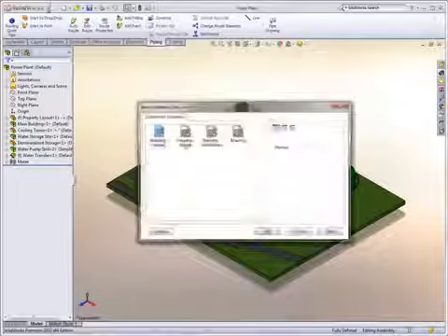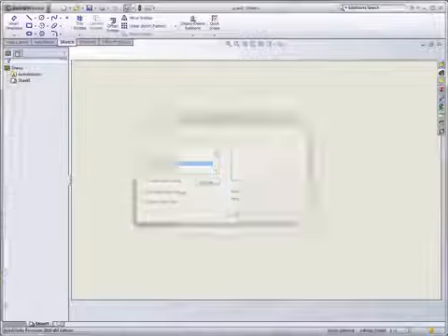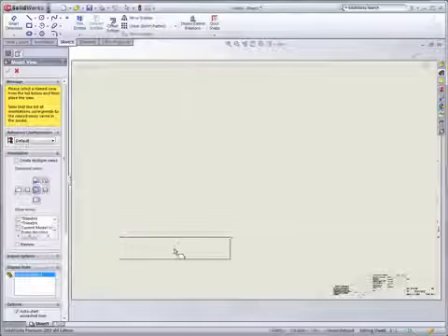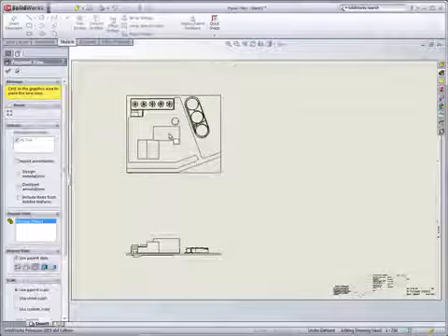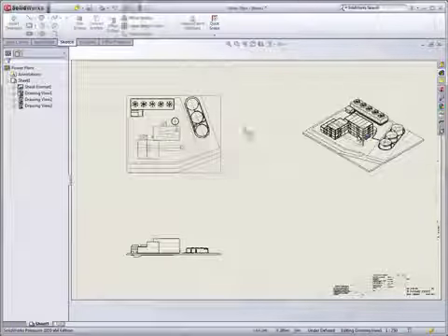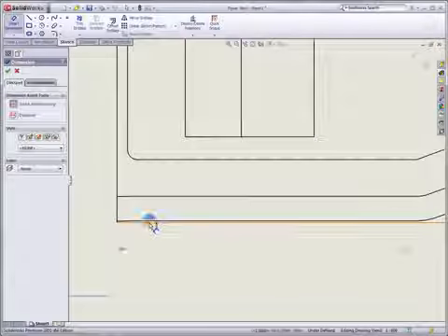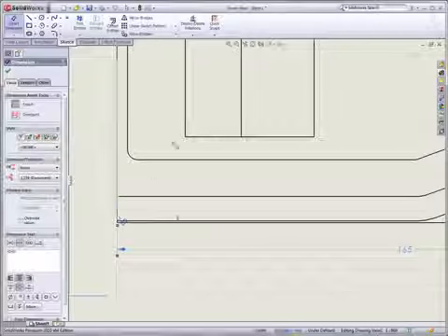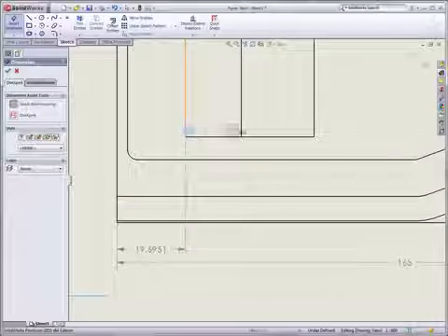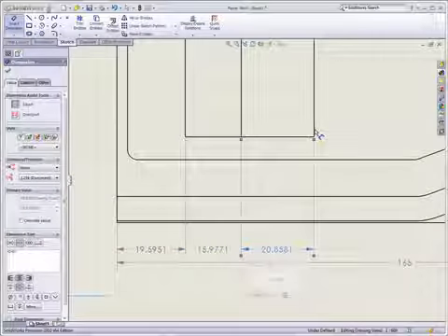Assembly drawings or general arrangement drawings are just as easy to create with SolidWorks. Simply drag and drop the desired elevation or plane views onto the drawing, and SolidWorks creates the views utilizing the 3D data. Detailing these views is easy with SolidWorks ultra-fast dimensioning tools. With SolidWorks, dimensions automatically space and locate themselves based on other dimensions and available space on the drawing.